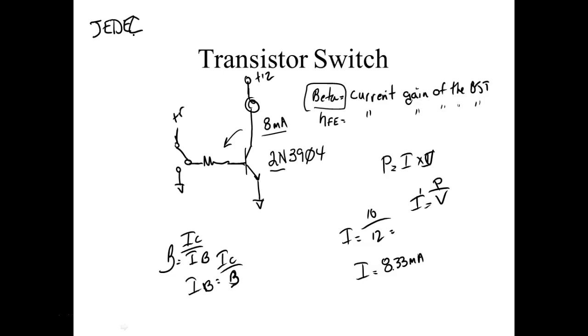So the frame of a motor, how big is it? How far is its feet apart? So that means if I want to get a motor, how long is the shaft? Then if I want to buy a motor, I don't have to buy it from the company that I get it from. All I got to do is get one that's got the same horsepower rating, current, and the same NEMA frame, right? You understand? So it means I can bring that same NEMA frame in and mount it into my exact spot.